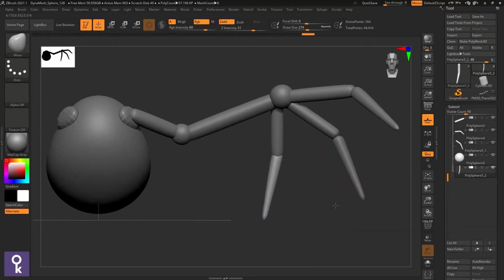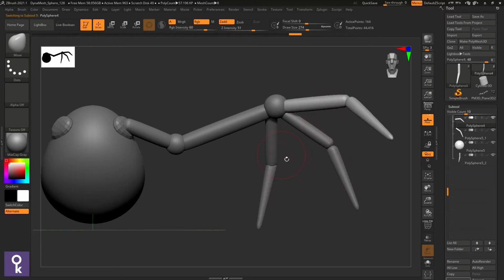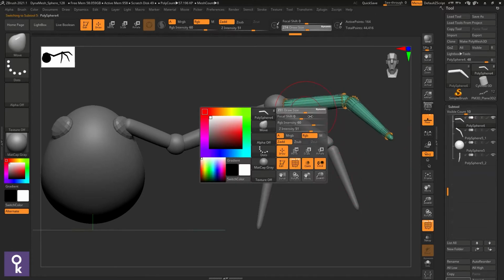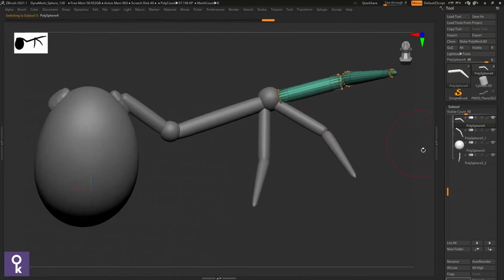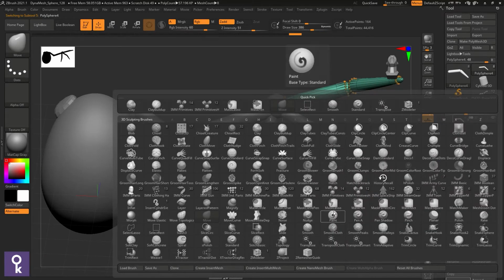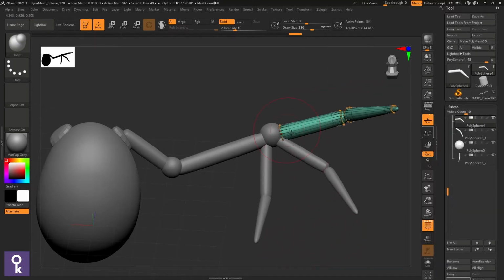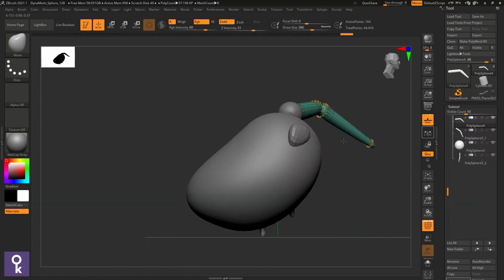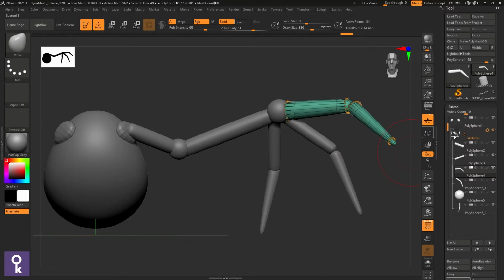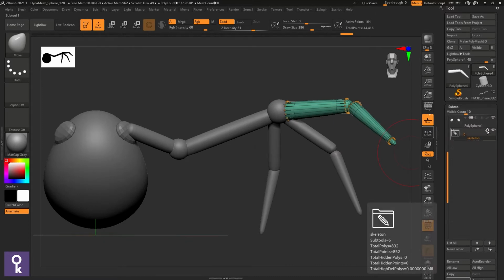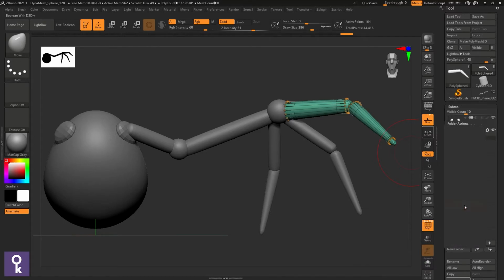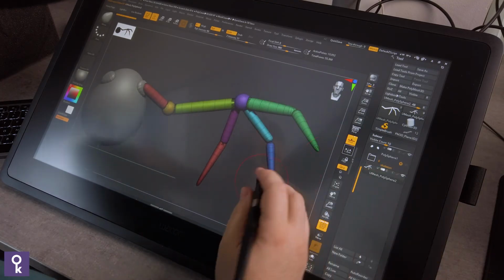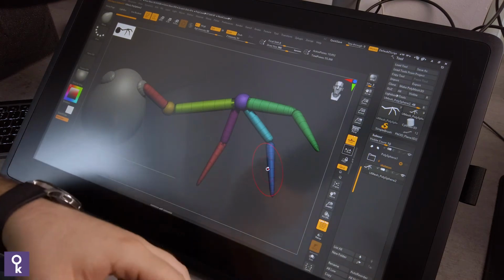So now that we have that, maybe let's select this one and maybe do a bit of an inflate, and go BMV and just move it around. Okay, once we're happy with the shape, we can go ahead and on this gear icon click Boolean with subdivision. So what it's going to do is Boolean everything with the dynamic subdivision that we added.